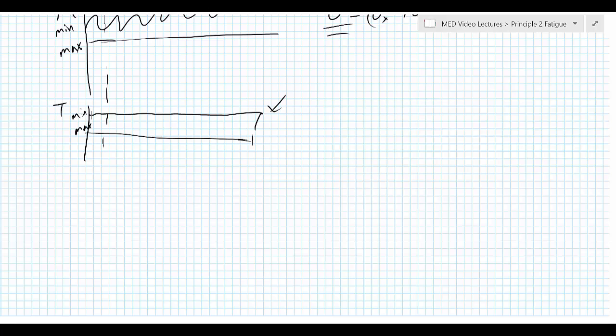So what we'll do is we'll come up with a new formulation for our mean and amplitude stress values, which is our modified mean and amplitude. So altogether, these look like this. We will look at the stress concentration factor, Kf, considering bending, and multiply that times the amplitude stress, which is due to bending.